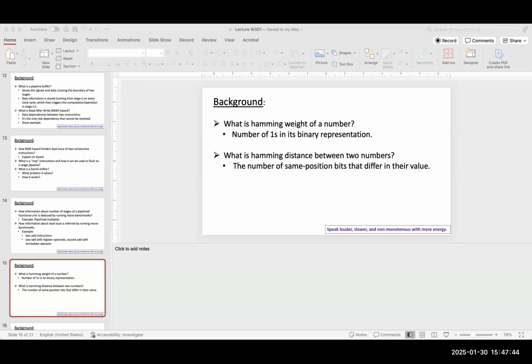Regarding the comment about the issue stage not knowing which ALU has the shifter or multiplier, doesn't it know that the ALU that handles the immediate instruction has the shifter? No. Whether you can execute an instruction with an immediate number is not related to the capability of the ALU. The problem is coming from the register file. Remember, you have 3 ports. For the ALU, it doesn't matter where the data is coming from, whether it's coming from the register or from the immediate part of the instruction itself.